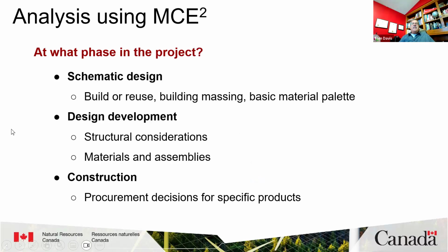So when to do this? I say early and often. So in the schematic design stage, why? Because we can make sweeping changes in the schematic phase that don't affect construction costs. Why? As the design evolves, again, you're going to pick structural materials, maybe details, assemblies. And then at construction time, it's time to order the concrete mix. Let's take a look at the EPDs and see what suitable mix is the lowest carbon for our project.